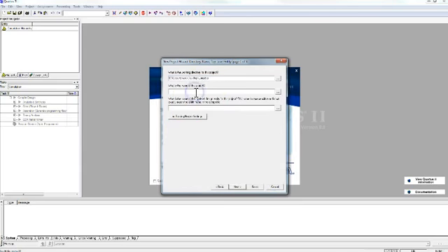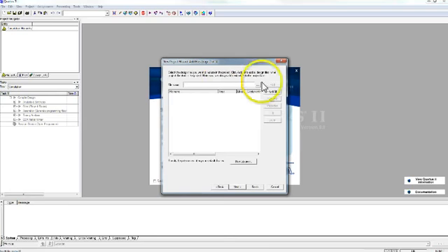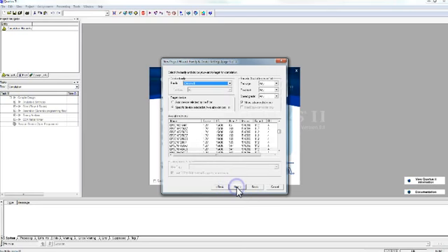And then I'm going to name this project. We want to make sure we don't use any reserved names. So avoid common names like adder and stuff like that would be reserved by the system. So in this case, I'm just going to preface everything with VA to avoid chosen names. And I'll just call it example. And I'll click next. I don't have any project files to include. We'll cover this later. This is my first project.